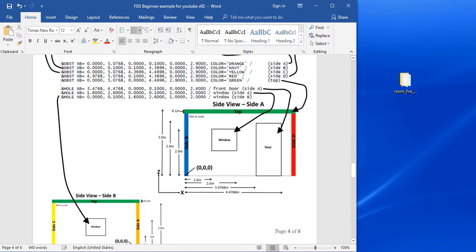One reason you might want to create a multiple wall structure or multiple piece wall is if you wanted, let's say you wanted the window to disappear. I don't know of a way to have a space there, have a material there when you're cutting a hole. So when I have a window, we'll do in another video I'm planning to make, I add a transparent obstruction in front of the window and have that disappear partway through the simulation. But I can't have it physically where the hole is. I have to have it in front of the hole.